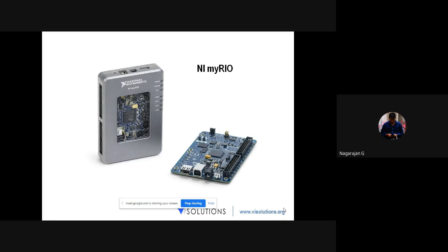The myDAQ hardware gets power through the USB cable only, so it is transferring the data through USB, and at the same time it is getting the power through USB. If at any instant you remove the USB connection, automatically the connection will be lost between your myDAQ hardware and your application software LabVIEW. So you cannot transfer the data. This means it should always be connected to the computer.